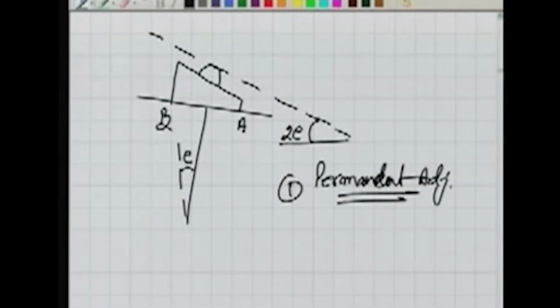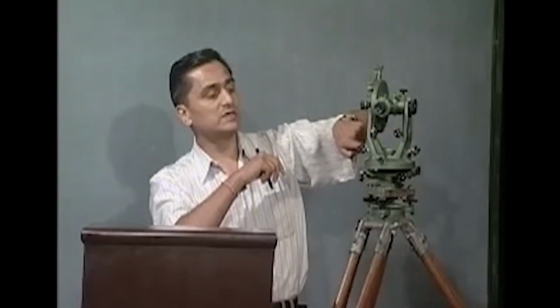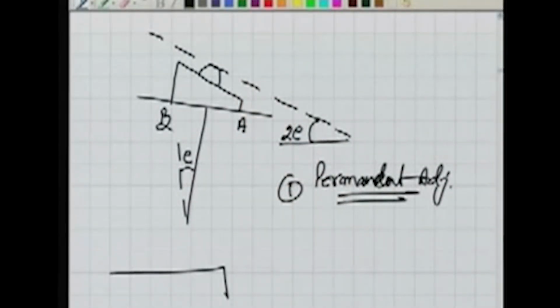all, as we have seen here now, after rotating this by 180, the bolt is here and the other side is here. What I do next, I eliminate, the bubble has gone out of center. So half of the bubble, whatever the bubble might have gone by, whatever is the distance, if I draw it here in the diagram, this is the center line. Let us say these are the lines for the bubble, and if the bubble is in center, it might look like this, but now the bubble has shifted here. So that's the total shift of the bubble.